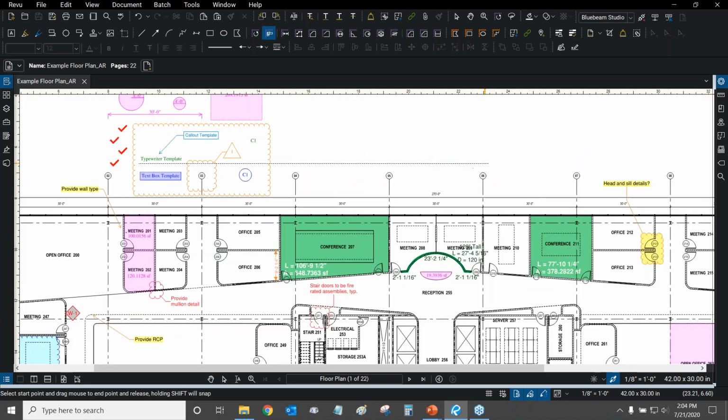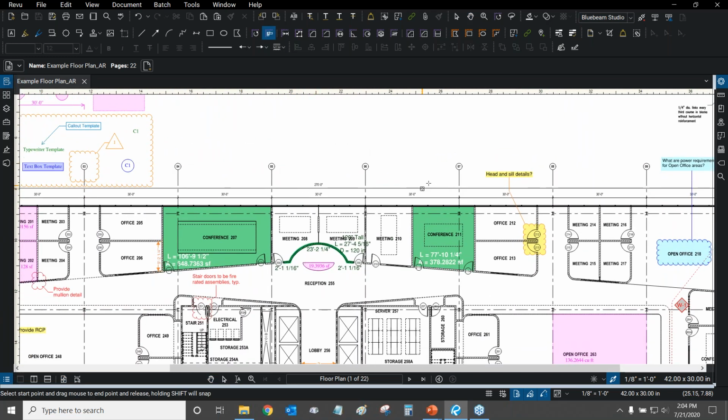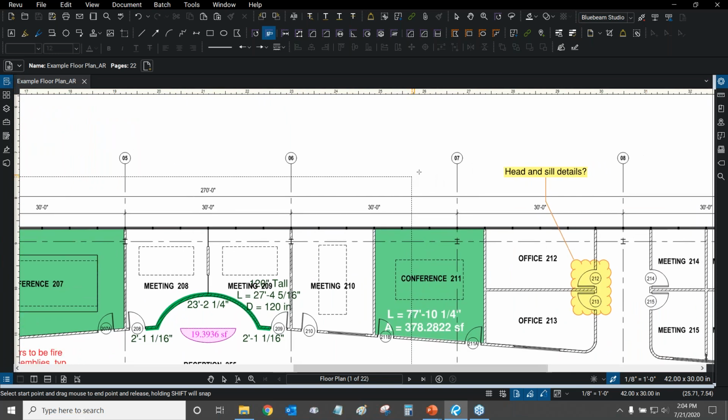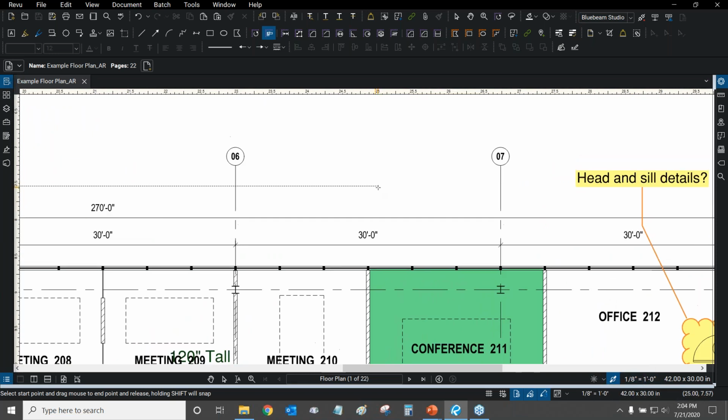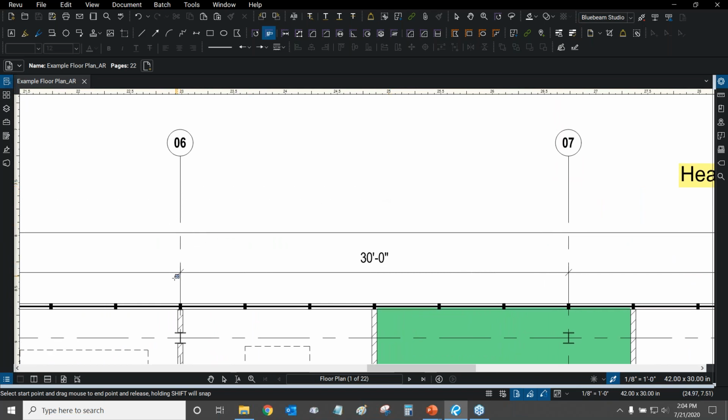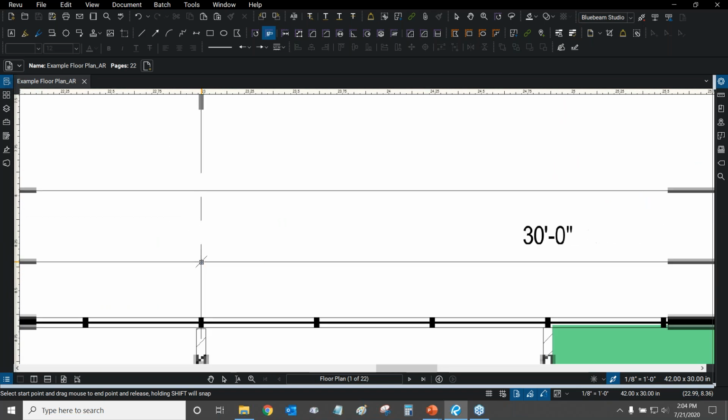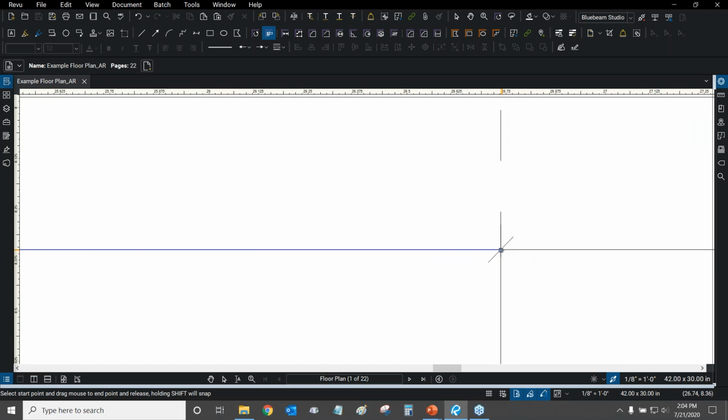Let's find an existing measurement, and we can use that existing measurement to determine what the scale is for the sheet. So if we didn't know that it was 1/8 of an inch equals a foot, by the way, you can see your scale by looking on the bottom right here, then you can determine what it is if you have an existing measurement. So let's click on this point first, and let's use this point right here.